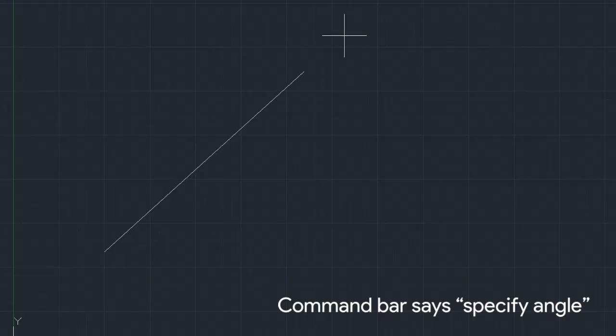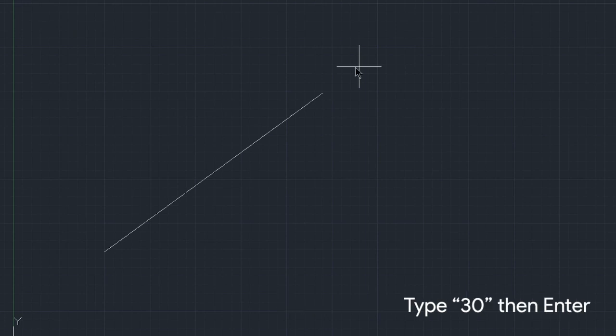Okay? So, karon nangutana na po siya. Unsa man nga angle imong ganahan? Ganahan ba kag 30 degrees? Sige, ato yung 30 degrees. Type nimo 30 degrees and then enter. So there you have it. You have a line that has a length of 15 and that is inclined from your x-axis about 30 degrees. Understood?